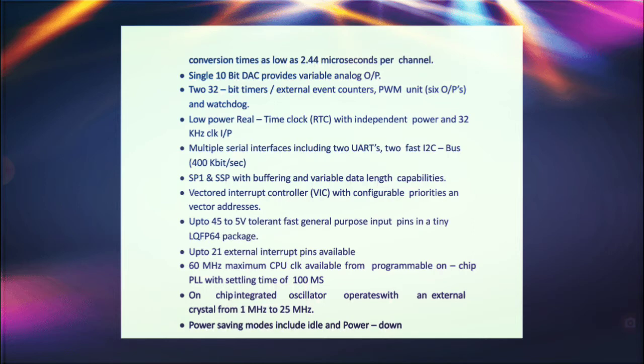Single 10-bit DAC provides a variable analog output. Two 32-bit timers, external event counters, PWM with 6 outputs, and watchdog. Low power real time clock, RTC, with independent power and 32 kHz clock input.